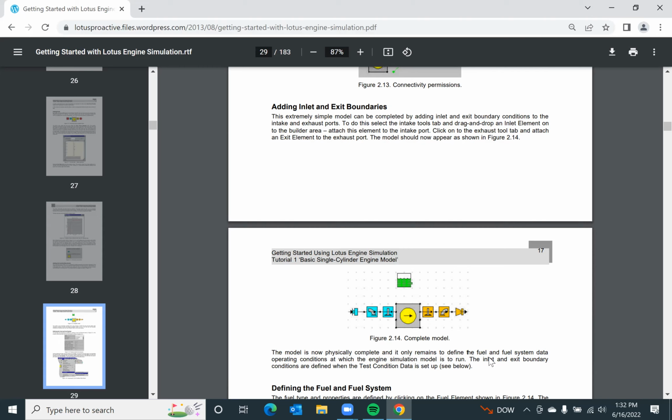Nowadays, we have fuel injection. So basically air comes in and the fuel spray is injected into the airstream. And then you have the gas pedal that controls the butterfly valve, which is the amount of air-fuel mixture that is entering the cylinder.